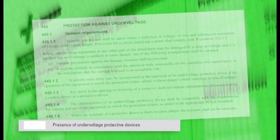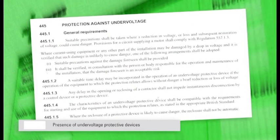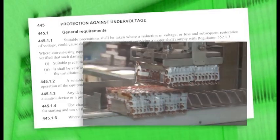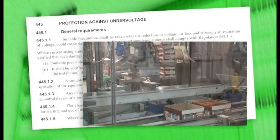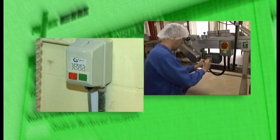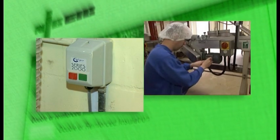Next, we have presence of undervoltage protective devices. Here, the inspector is checking that the requirements of section 445 have been met. For example, that suitable precautions shall be taken where a reduction in voltage, or more commonly, a loss of supply and subsequent restoration of that supply, could cause danger. The inspector should check that any undervoltage devices installed, usually in motor starters and control equipment, conform to the design requirements for that particular part of the installation.